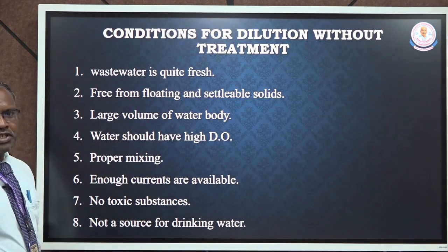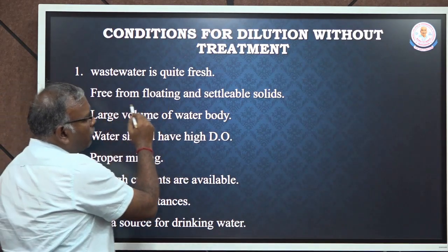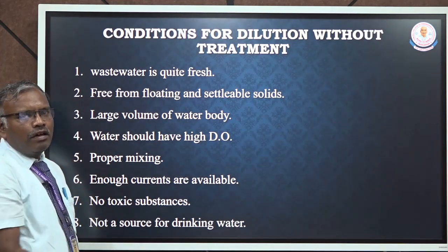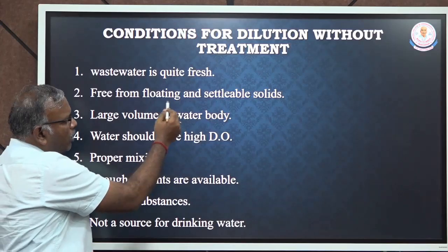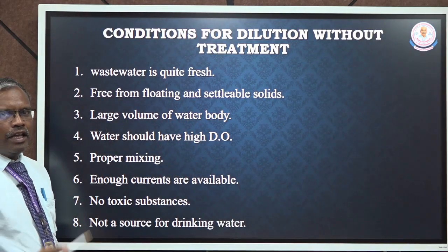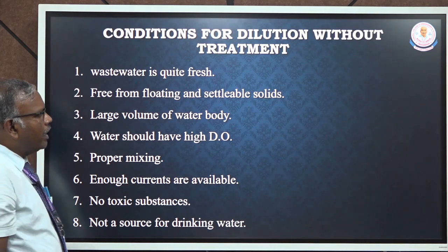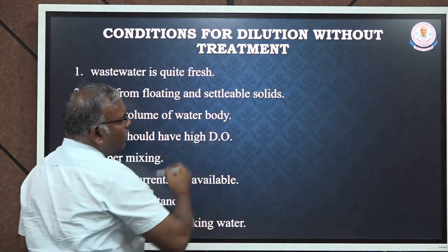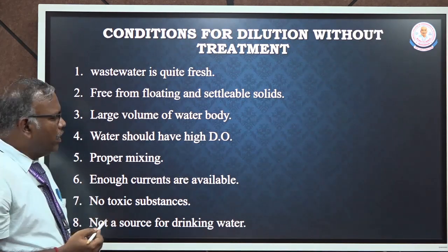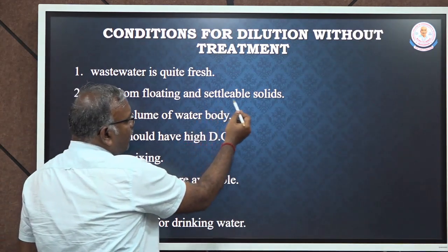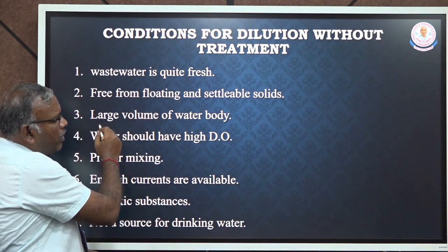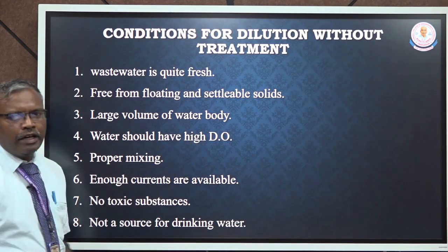It should be free from floating and settleable solids, because floating substances may create an unpleasing effect on the water body, and the settleable particles may get deposited, undergo degradation, and lead to the production of foul gases in the water body.